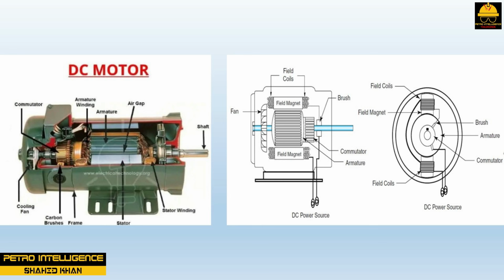The armature is a cylindrical device attached to a driveshaft that is designed to become an electromagnet when current is passed through it. During operation, the armature rotates through the magnetic fields. At set intervals, the rotation cuts across the magnetic fields, reversing current flow. This process occurs on each half rotation of the armature.